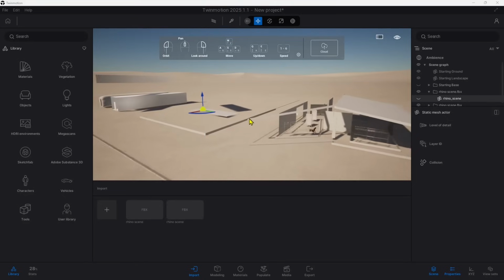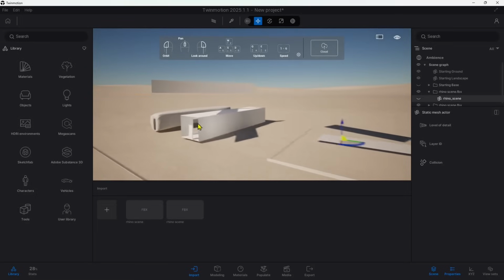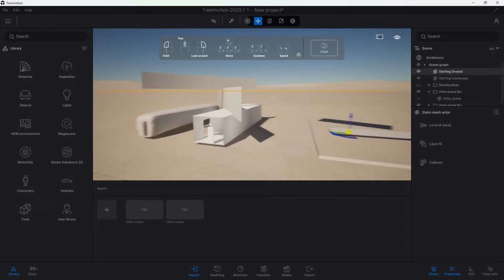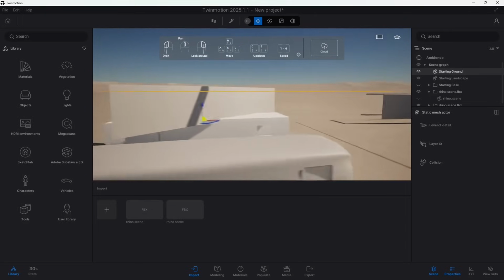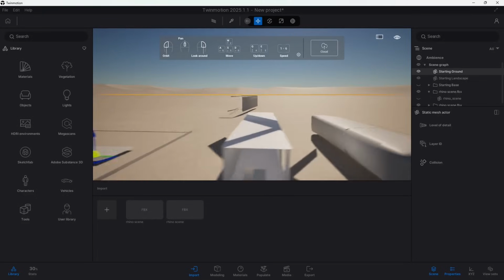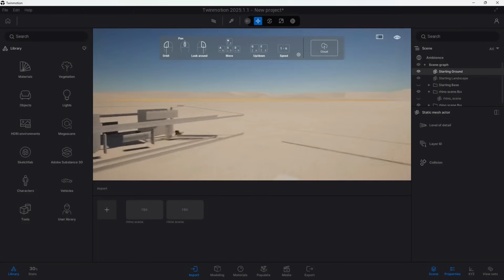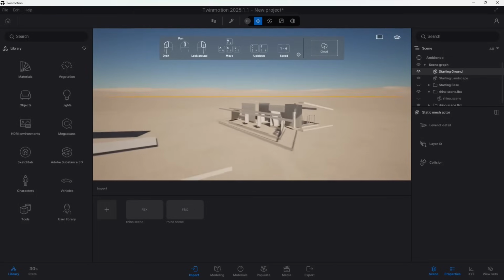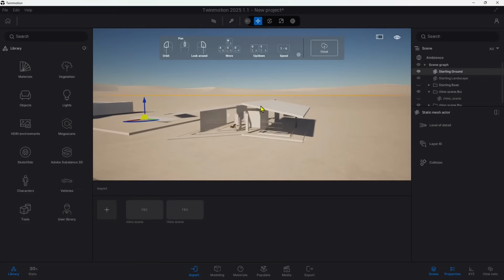And there you go. So something here is working, something is not. Mesh objects are definitely working, even though we need to check on some geometry. And also the SubD smoothed surface is working great, but all the solids here made with Nurbs modeling are gone, so they're not visible. And that's an issue.